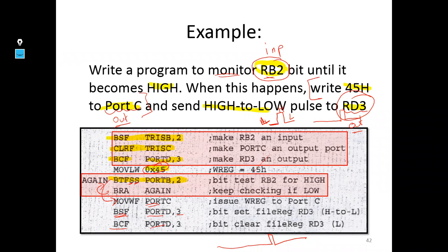Okay, let's have here B3. And B3 is connected to the capacitor. And the capacitor is connected to the ground. Okay, now you use bit set 5, port B, 3. So you have here set. If you have set, and here you will make 1. Okay, but the capacitor is discharged. So the capacitor will start charging.